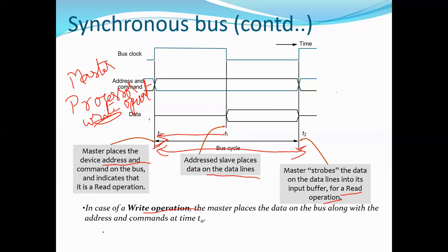If it is the write operation, data is put here by the processor, and data will be present in the data bus till the end of this T2.